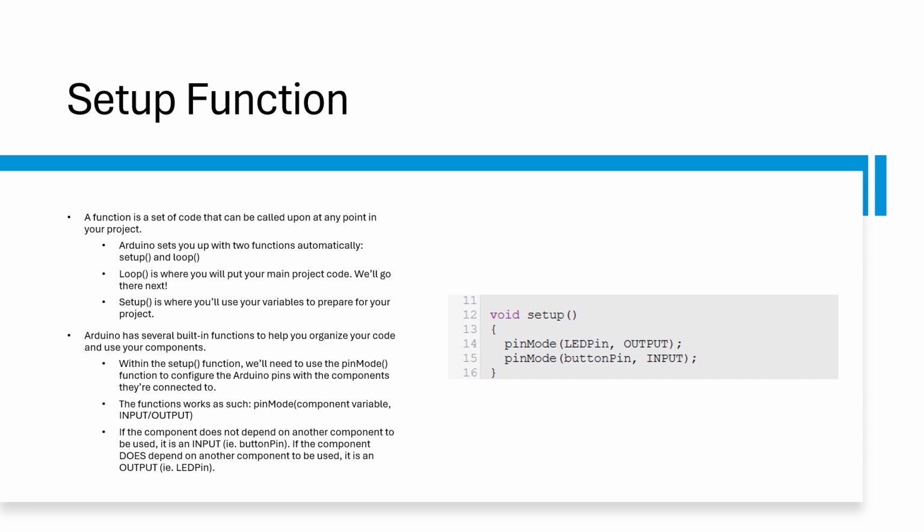Next, let's look at the setup function underneath. A function is used to store parts of code that can be called any time in the program. Arduino uses thousands of special functions in its programming language, including setup, which is referenced and called once at the start of the program. As its name suggests, it sets up some parameters before the next section of code starts.